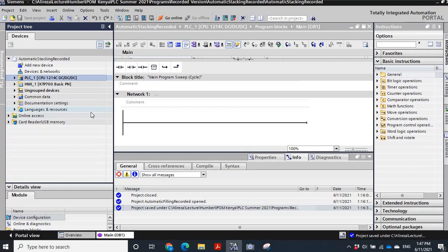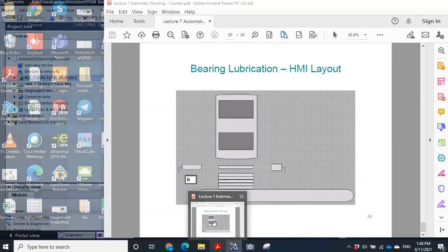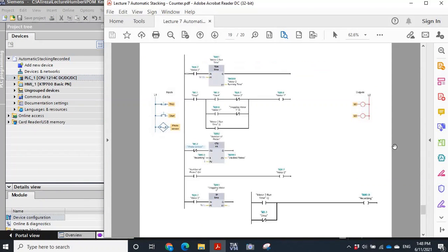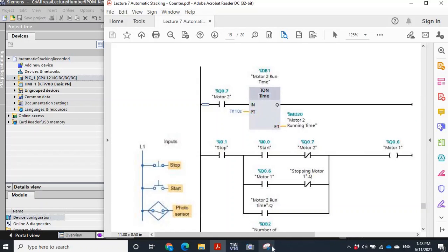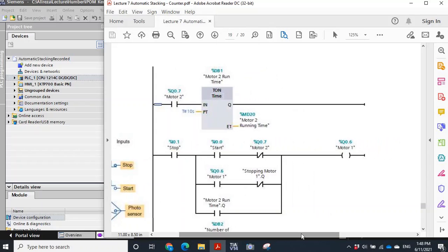Okay, again the PLC file is ready, and we're going to build the program over there. So let's again look at the program. Let me enlarge the size a little bit. Okay, that's the size. We need a normally open here and then an on-delay timer and also this structure. So let's first build this part and then the structure of that, and then go through this.